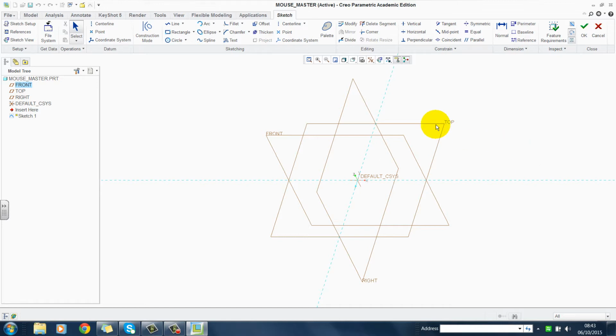The simplest way is to draw two center lines. I'm now going to select a circle and let it snap to the center line running up the page anywhere. Left click once, move the mouse out, left click again to complete the circle.